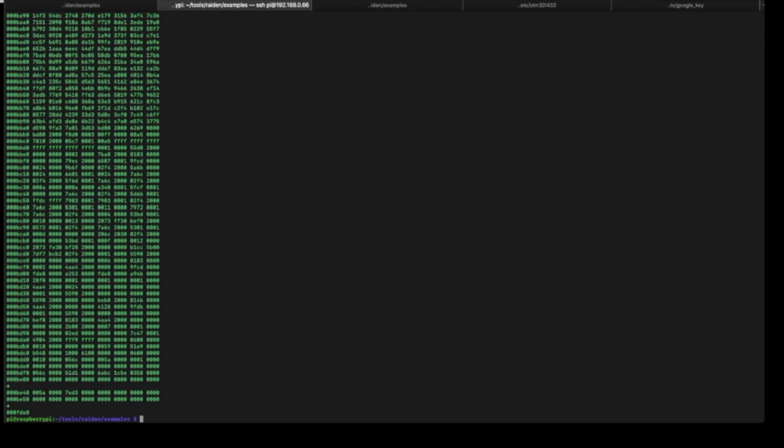And this data could be anything. It could be some information about a stored secret key. The severity of the problem depends on what was after the USB descriptor structures. So if there is some memory there with sensitive information, it will be spit out over USB, and that's definitely a vulnerability that we can use.